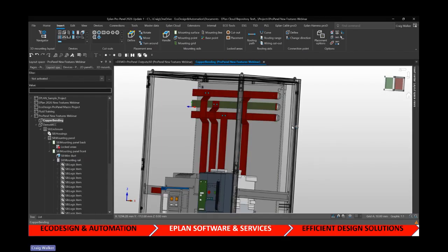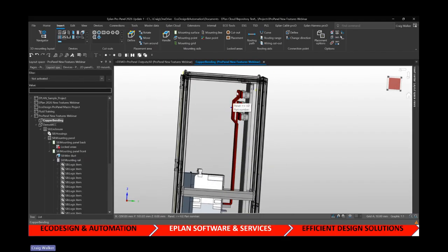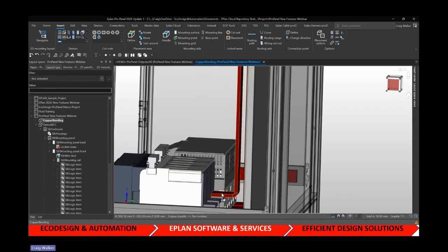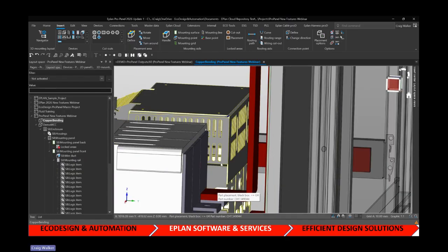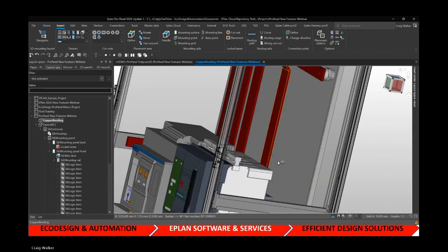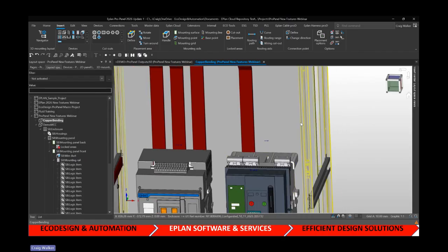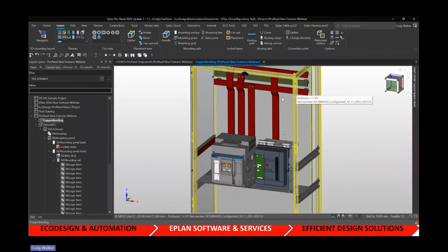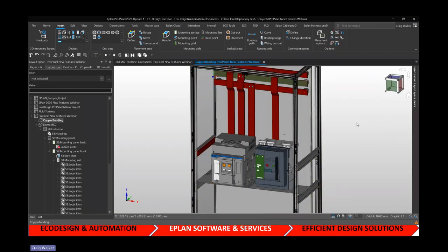And if everything worked, it's coming up perfectly over those two rails, down, and sitting right on that plate where it's got to connect to. Then I would just place a bolt hole on there. That's how you create the forms. If you stuff it up, you can open up your form, edit it again, use your measuring tool to see what's missing, and recreate the copper bar. And then place it again, and obviously give it a label.